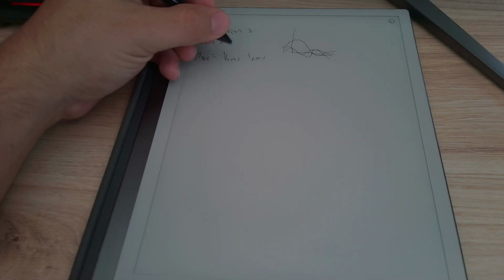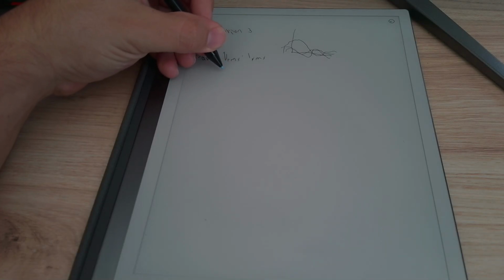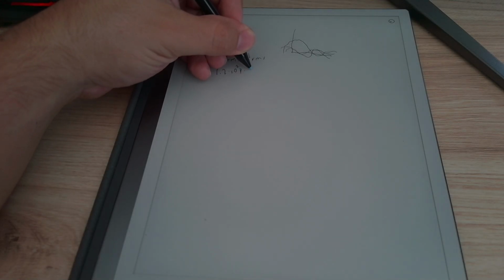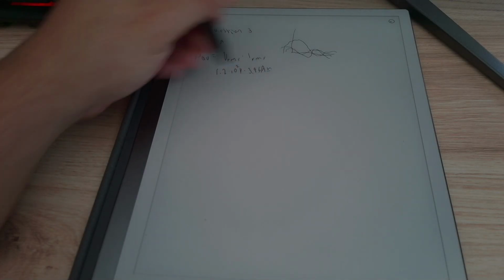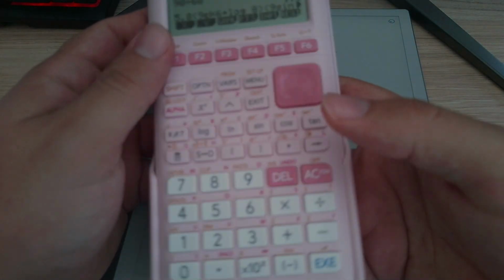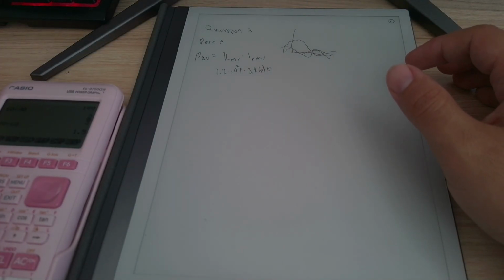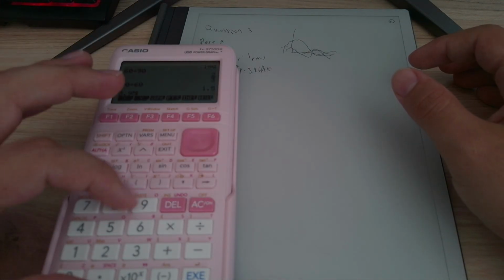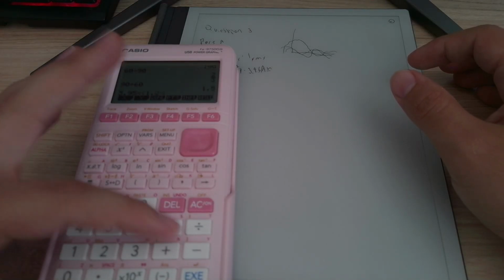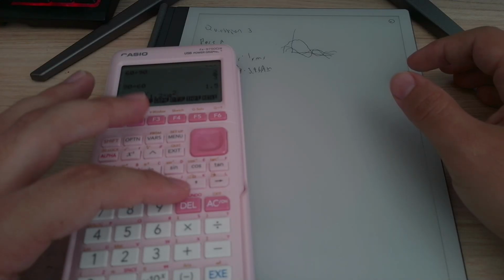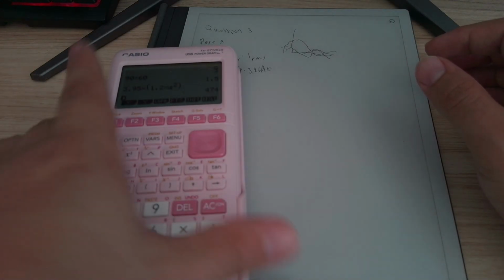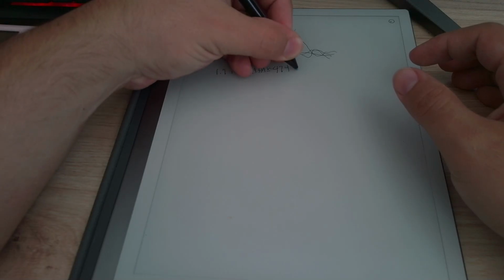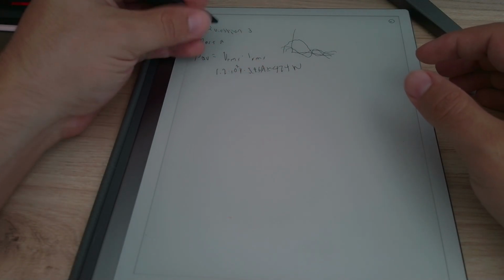So we're going to input the values given to us, which will be voltage of 1.2 times 10 to the second volts times 3.95 amps is equal to, calculator here, 3.95 times 1.2 times 10 to the second, which is 474 watts. It will be in wattage. 474 watts. That's for part A. Now part B.